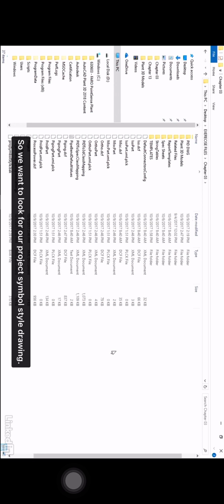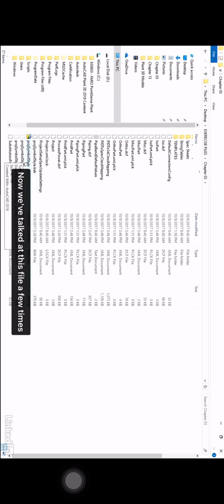So we want to look for our project symbol style drawing. Now, we've talked about this file a few times through the lesson already, saying that we cannot rename, delete, modify, or purge this file. The reason is this is the file that contains all the information about the project. When we go in to make changes to our project manager, the first thing that happens is the project symbol style drawing is opened, allowing us to permit changes. If we right-click and change the properties to read-only, that effectively locks the project manager and won't allow changes to be made at the project admin level.